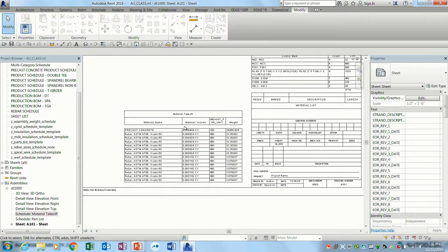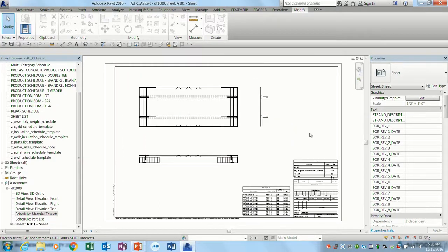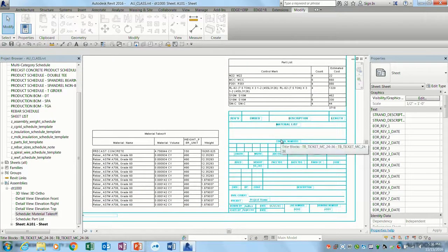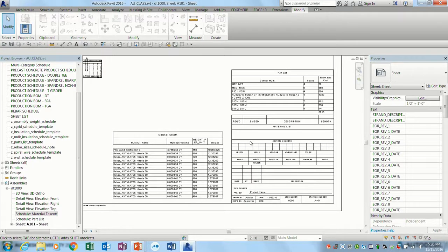So that's a little bit about how we can utilize schedules, utilizing hidden fields, calculated fields to create new values or fields or columns of data that we want to show based potentially on calculations that we've done on other fields in that schedule. Hiding fields, grouping and totaling, and what else do we cover? Anything? Should ask you. Pop quiz. Okay, so any questions about schedules right now? Anyone bored to tears? All right, that's good.